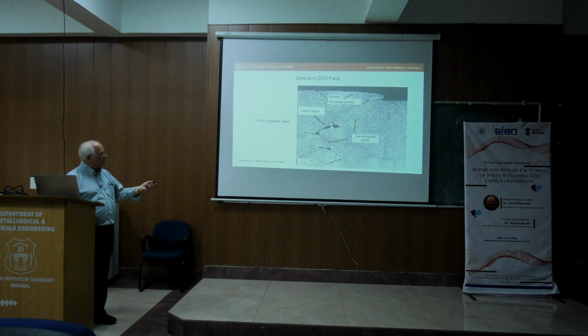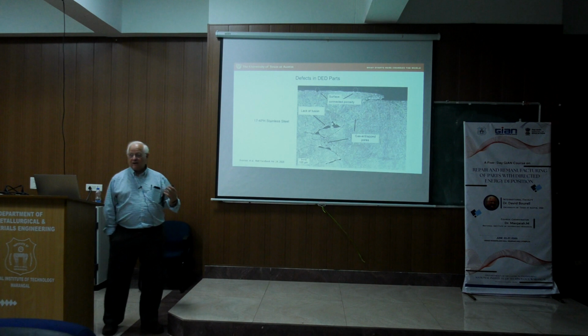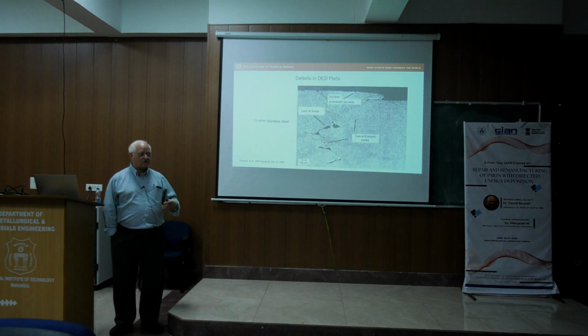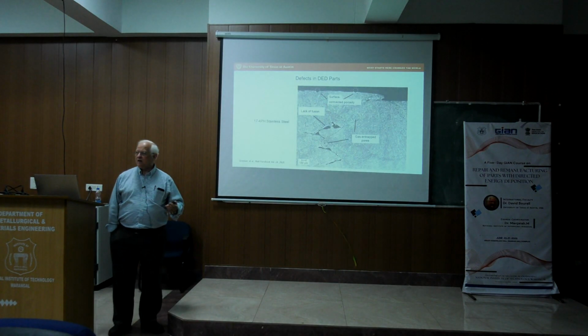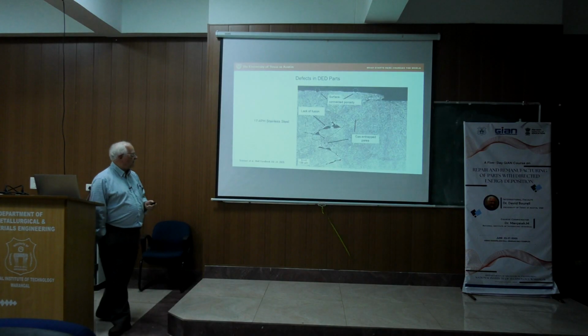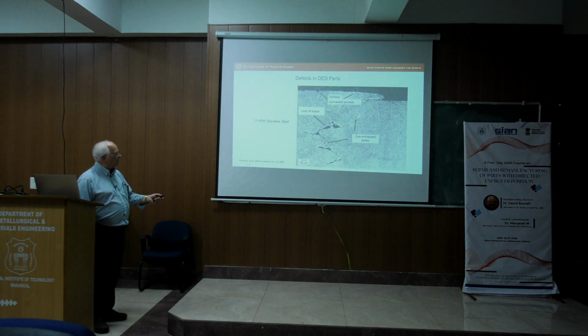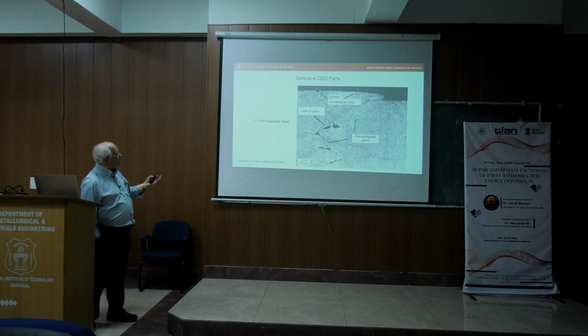They don't have the look of keyhole porosity, and also if we're having fusion errors, you wouldn't expect to see keyhole porosity because they happen at different power settings. So this is most likely porosity that came in with the feedstock, which I assume was powder.